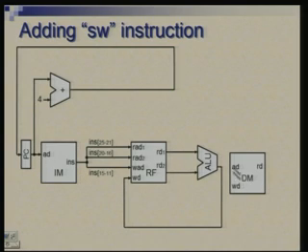Okay. Now, we have positioned the memory here, we now need to connect the inputs and outputs for this. So, first of all, the address, as I mentioned, will be produced by performing an addition. So, we will use ALU for doing the same thing, okay, because load store instructions do not require other arithmetic operations to be performed.